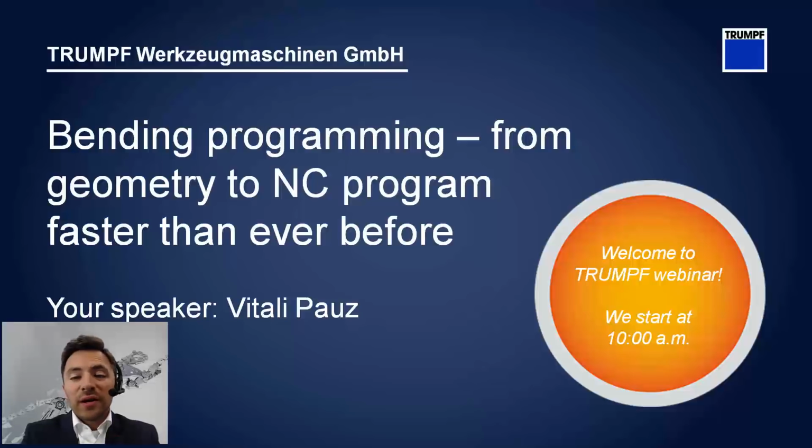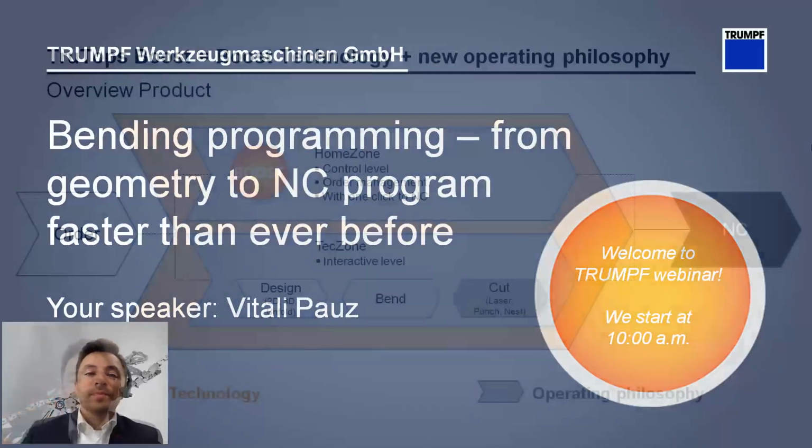We will also learn how to add special tools and special materials. Thus, the bending sequence and the tool setup and the backgauge finger strategies of unfolds can be optimized for production the fastest way possible. Through the immense time saving, using the automation, the programmer only has to intervene where it's necessary. And therefore, with TruTops Boost, you generate bending programs faster and reduce the non-productive time of the machine.